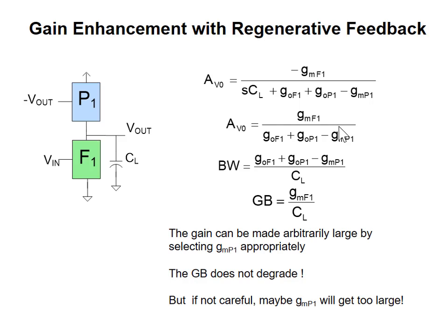So let's look at an op amp. You can go back to any of the op amps you looked at in 230. We also looked at measurement characteristics in the lab in this course. Here's what the gain characteristics typically look like. You have a DC gain A0. You have this pole here, omega 1.